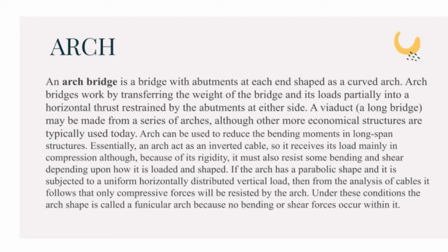If the arch has a parabolic shape and it is subjected to a uniform horizontally distributed vertical load, then from the analysis of cables, it follows that only compressive forces will be resisted by the arch. Under these conditions, the arch shape is called a funicular arch because no bending or shear forces occur within it.